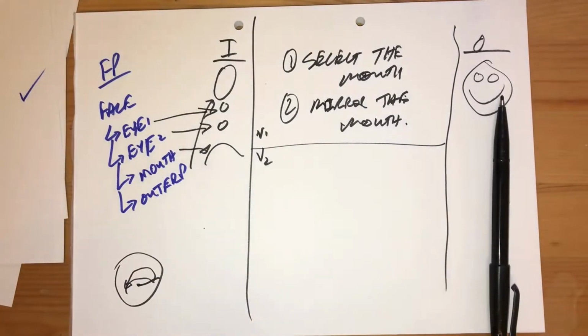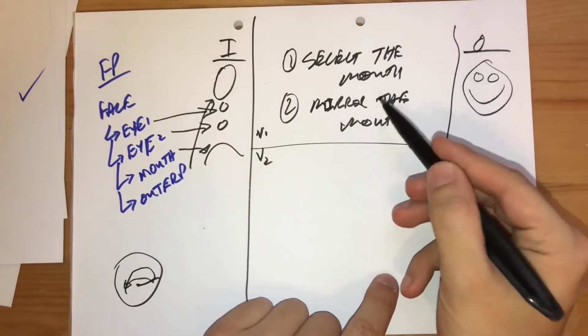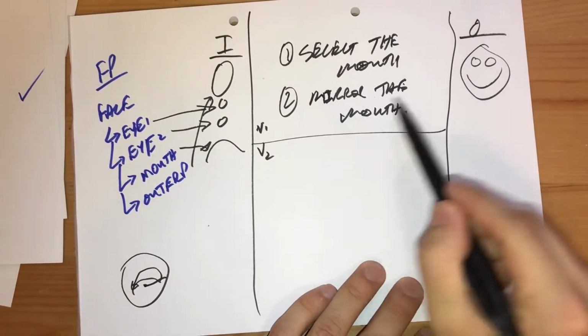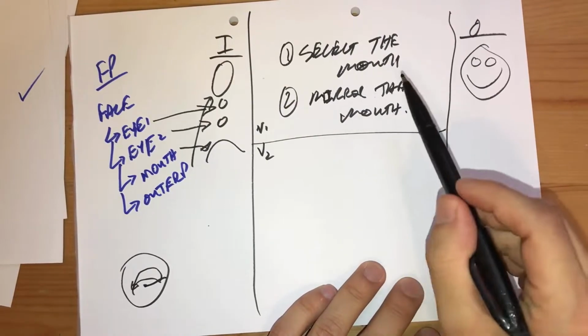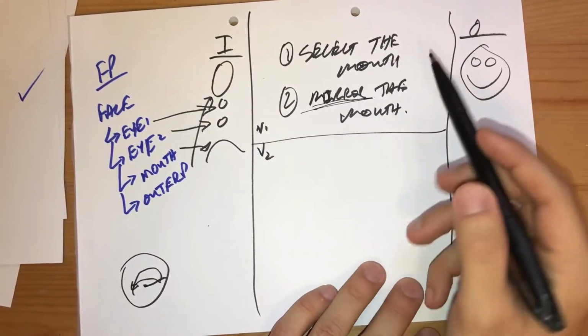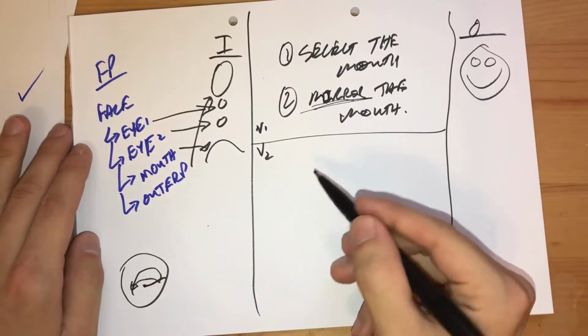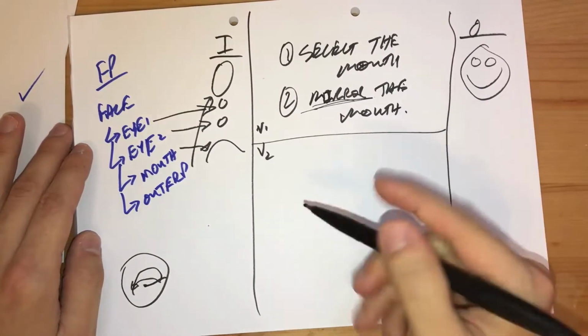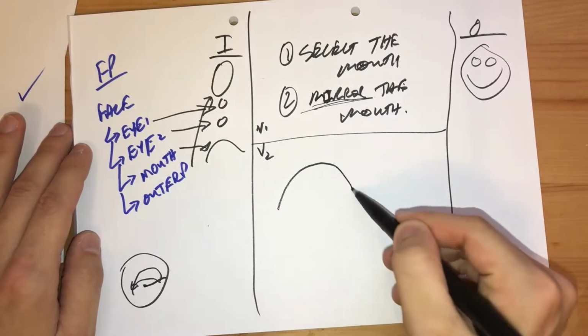So in Grasshopper, we had noticed that the main issue with the second part of our algorithm is it's not well defined enough. Just like before, we said mirror the mouth. And we didn't appreciate that when you have a mirror, the input needs a plane.